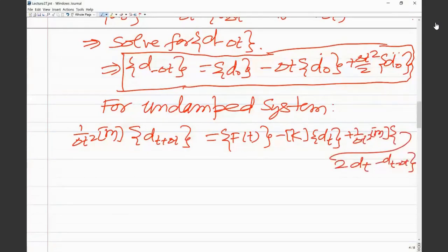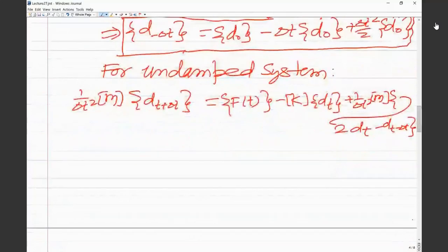So this is the equation, and we use a diagonal mass matrix. For example, if you use a lumped mass matrix, m would be diagonal, and if m is diagonal, then you don't need the solution of simultaneous equations. For each degree of freedom you can write the solution directly. In finite element analysis most of the time is spent on solving the simultaneous equations, but here you can avoid that if you use a diagonal mass matrix.